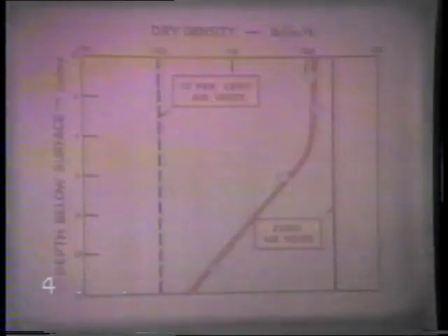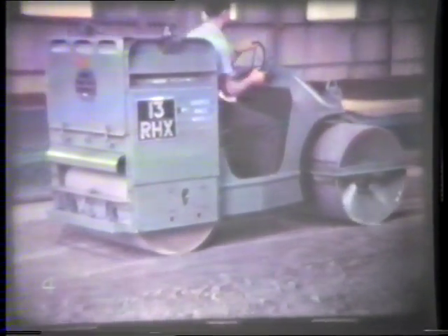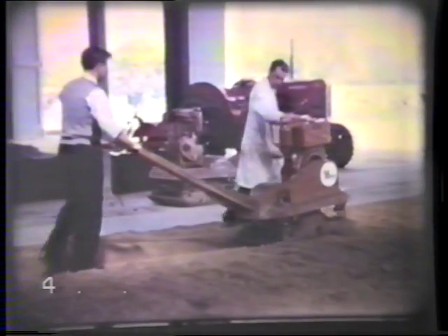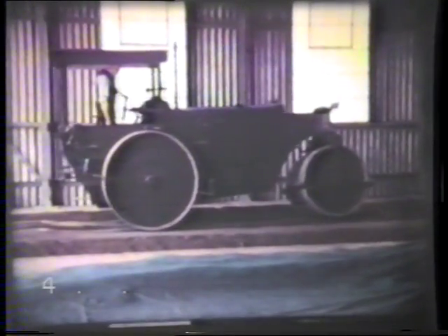A knowledge of the 3 curves obtained on the test soils for various types of compaction plant enables the engineer to select the most suitable machine to be employed for any particular work. He can also specify the most satisfactory and economical method of operating the machine. Only in this way can the necessary standard of earthwork construction be achieved at the minimum cost.